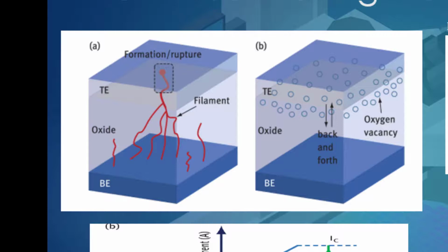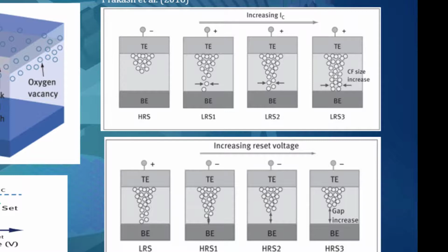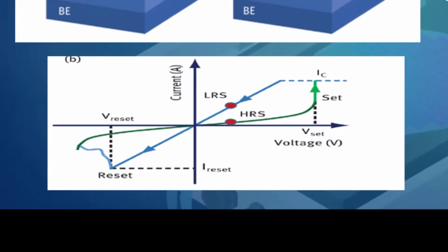These memory stores ideally can hold more than 2 bits of data. Right now, our semiconductor devices like MOSFETs can only function as ones and zeros, which is just turn on and turn off. But a memory store could have beyond that. One memory store cell could have 3 to 4 bits of data. It can happen because resistance is analog in nature. It is not discrete. In actuality, some research found that it can happen by increasing the compliance current, which is some sort of current threshold, or by increasing the reset voltage of the device.